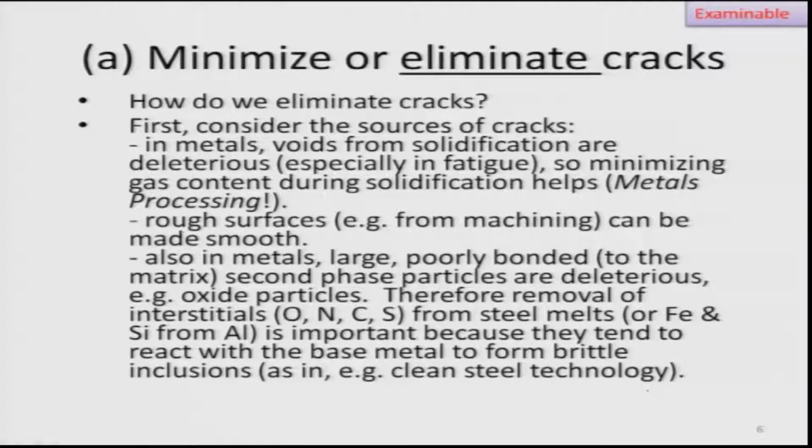Suppose you have a dispersion strengthened alloy, you have added something, if you add oxide dispersed nickel or oxide dispersed steels, these are available in actual applications, then the bonding between this oxide and the steel or oxide and the nickel may not be perfect, may not be good. Basically because ceramic and metals may not have a compatibility as far as bonding, as far as thermal expansion is a concern. So, therefore, there is a chance of void nucleations.